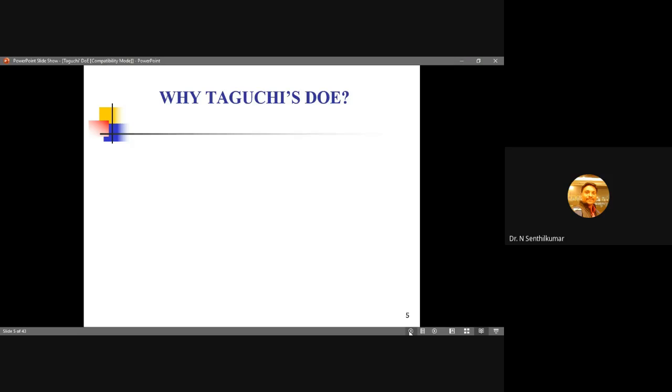That is one more advantage of RSM, even though it has the disadvantage of a higher number of experiments compared with Taguchi. Why the repetition? To eliminate the experimental error. In Taguchi also, we incorporate that by means of replication or repetition. At the end, we can see what the replications and repetitions are.